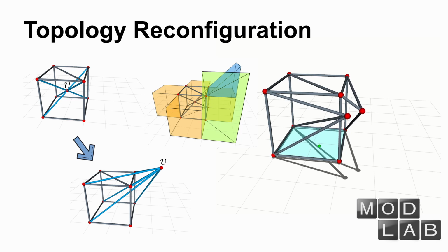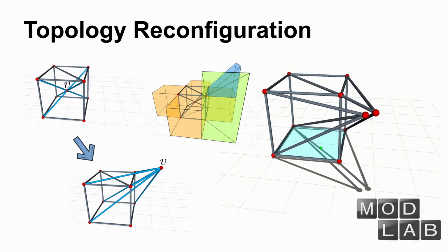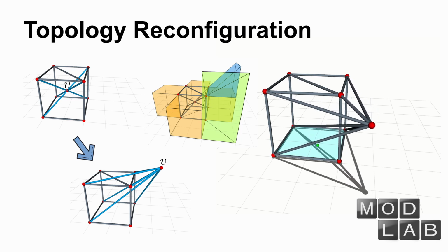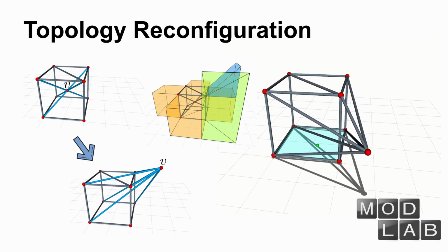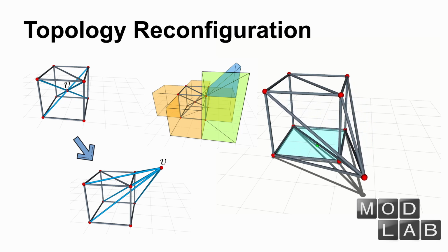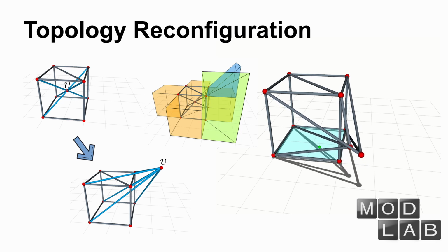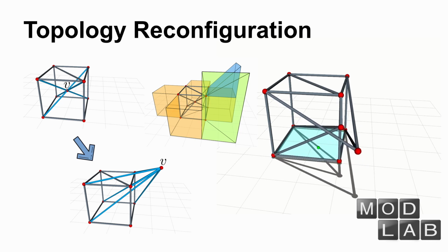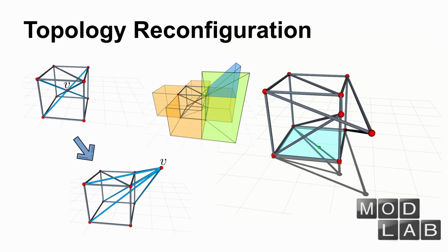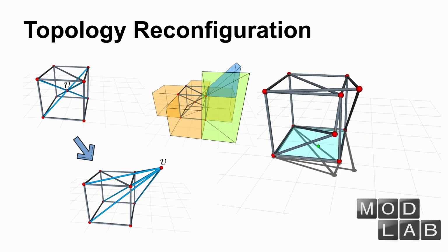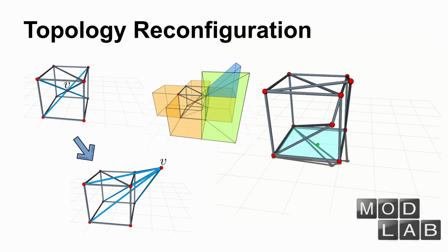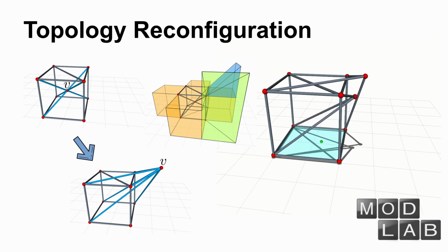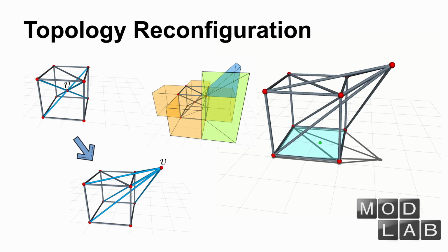If splitting the node inside the truss, one node has to traverse a region leading to singular configurations. After merging these two nodes inside the green space, split the node in another way so that they can be moved and merged inside the blue space and moved to the goal position. With 1,000 trials, the average planning time is about 86.5 seconds with a standard deviation of around 2 seconds, and the success rate is 95.9%. In these trials, the maximum planning time is around 92.9 seconds and the minimum is around 80 seconds.